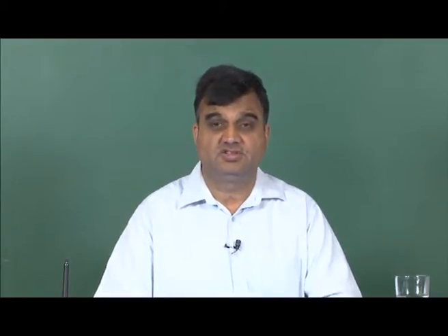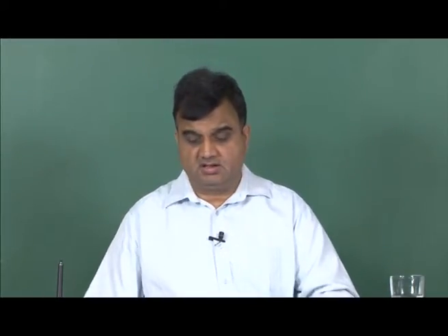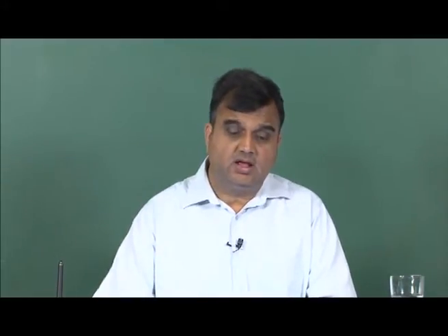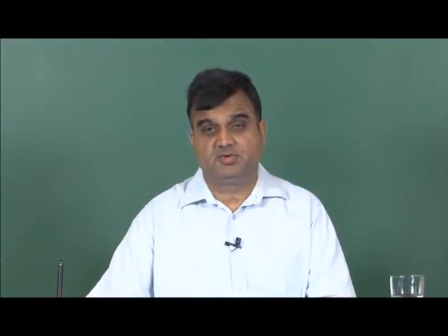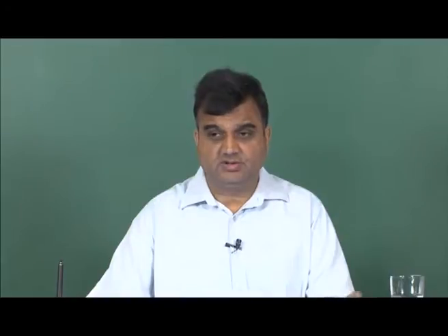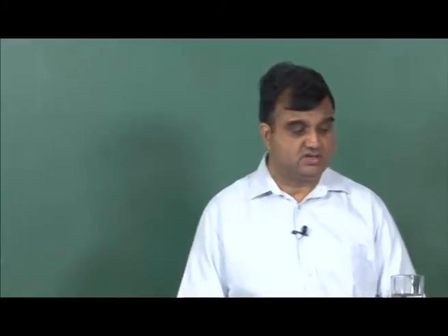Today is the last day of this ongoing week, which is the 9th week of this course. We have been discussing the formulation of stress strain constitutive relationships for different types of materials, and we started with anisotropic materials, where we found that it has 21 independent elastic constants. Especially orthotropic material in 3D has 9. Material which is transversely isotropic, that is its properties in a particular plane are isotropic, has 5 elastic constants, and today we will discuss